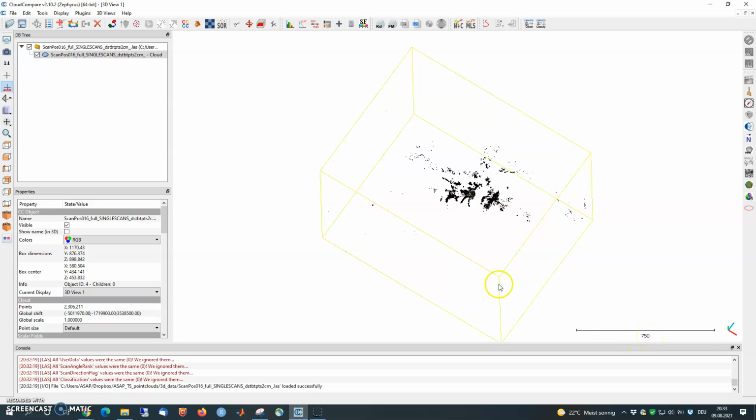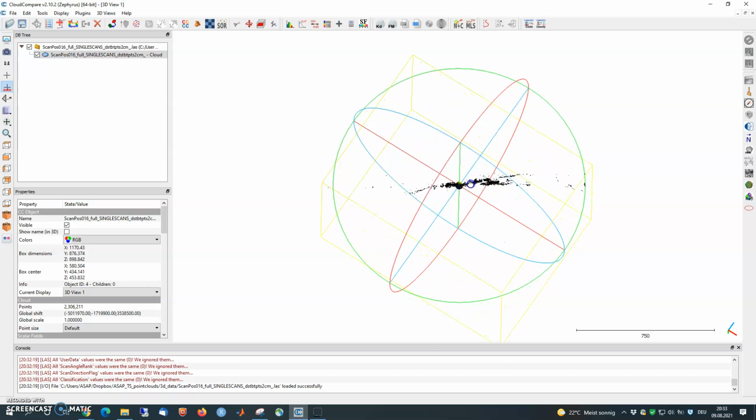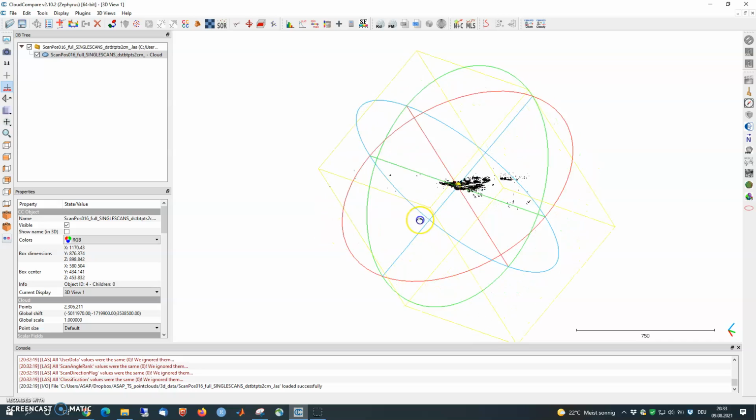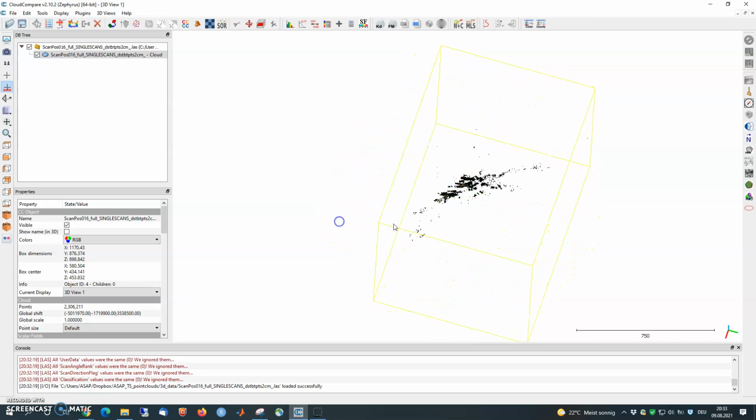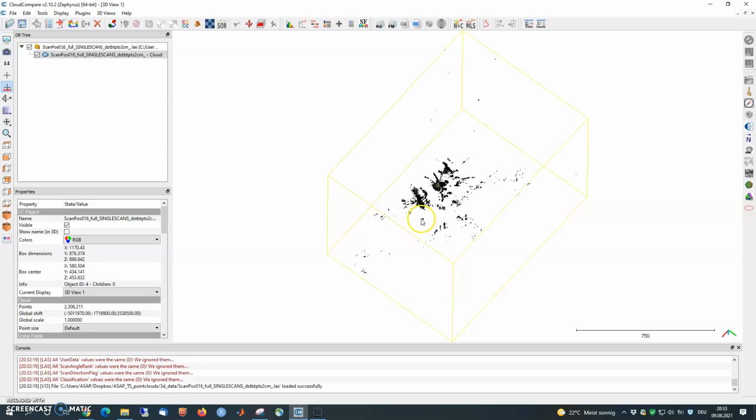That stands for meters, as long as our coordinates are in the correct system. And we already can get a feeling that this is quite a huge file. Once we get lost, we can press this 1 by 1 button, which is global zoom, so it will cover all the point cloud again.